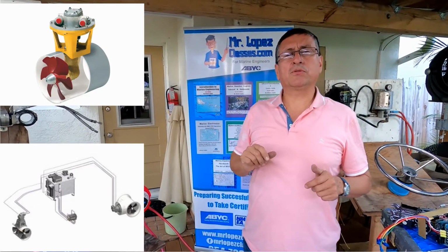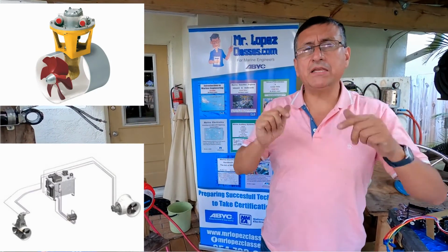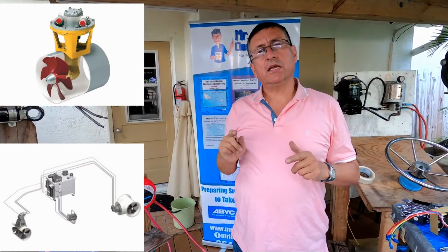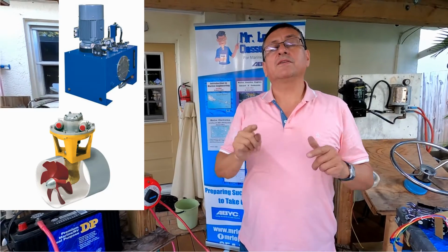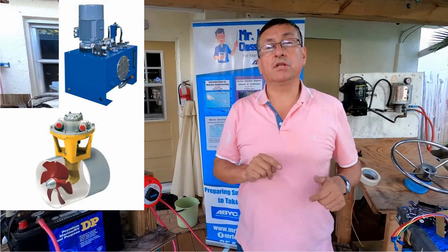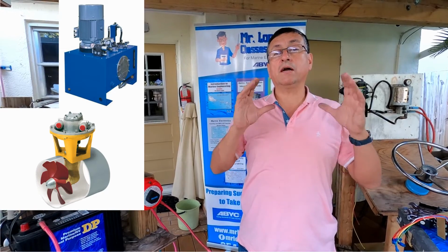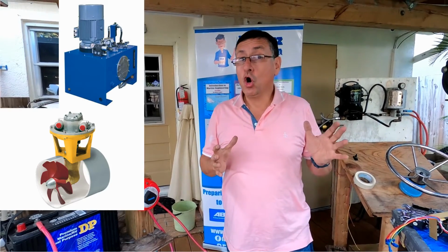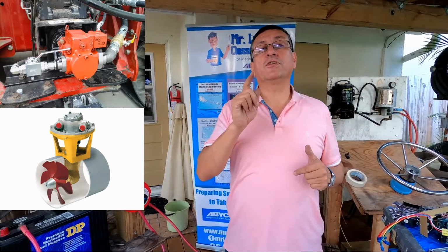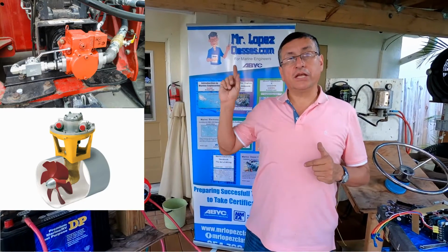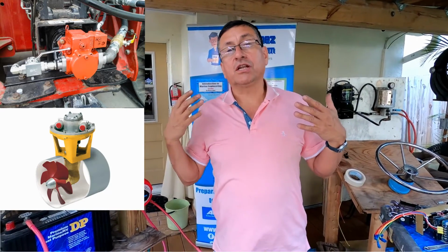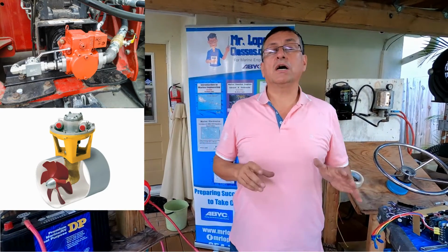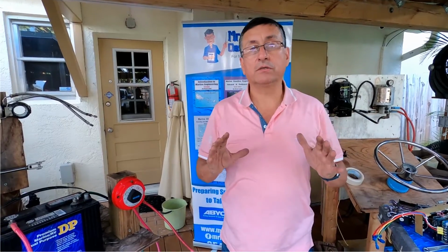This is another great example of bow thrusters and windlass integrated in a central hydraulic unit. That hydraulic bow thruster is highly efficient in mega yachts, in big boats. This is the bow thruster recommended, hydraulic, and the hydraulic motor on top receives the power from the central hydraulic unit. The central hydraulic unit normally has the reservoir on the bottom and the electric motor on top, AC or DC. Or the hydraulic power is coming from the PTO, and the PTO is connected, you remember, to the transmission of the main engines or directly to the crankshaft of the generators. Those are the sources of hydraulic power.